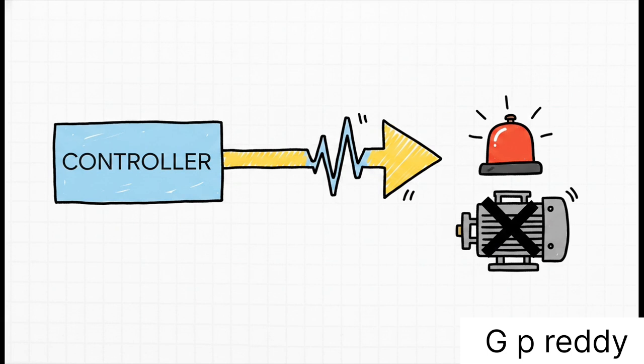Finally, to complete our core 4, we have the digital output, or DO. This is the decisive, absolutely uncompromising on or off command sent from the controller out to the real world. When the controller processes that a dangerous pressure limit has been reached, it is definitely not sending a gentle analog suggestion. No, it fires a digital output to instantly trip a relay, blast an emergency alarm, pop a solenoid, or just completely kill a motor. It's literally the controller shouting, "Do this action right now."